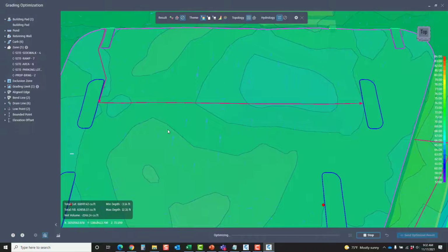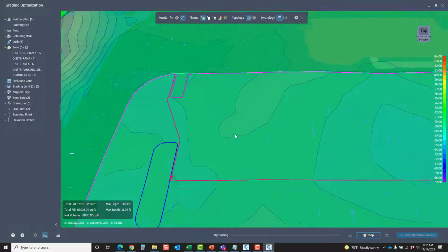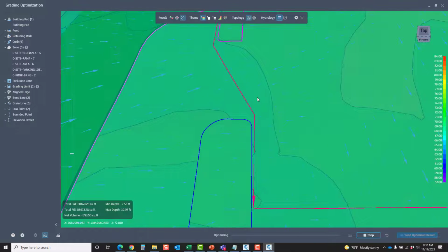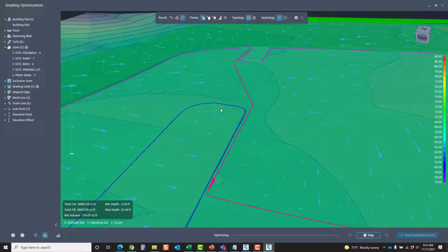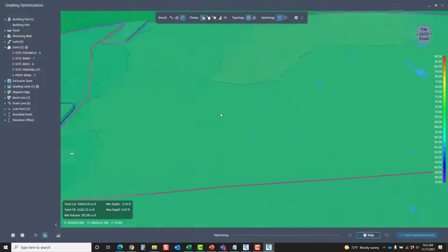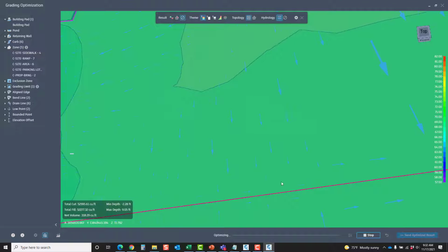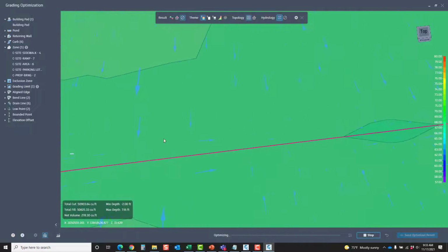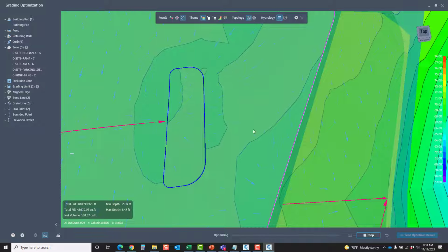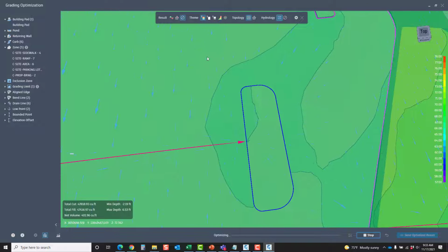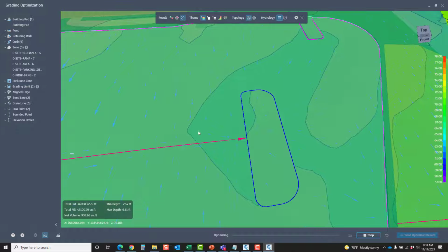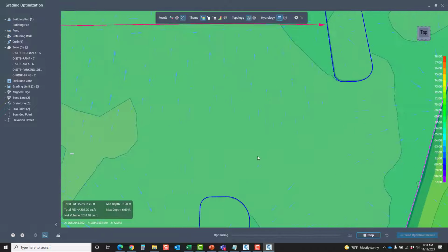Or I could look at the lines, the hydro lines, and see that from these drainage lines that I placed, the direction in which they have been drawn is going to change the pitch of my slope. So you can see my slope is going to change here. It's going to come down. And anything adjacent to this line is then going to come to this line, flow this way, and then end up right here. Notice how the other lines outside of it also run to the nearest either line or point. So this is all going to be pitched this way because that is the nearest drain line.